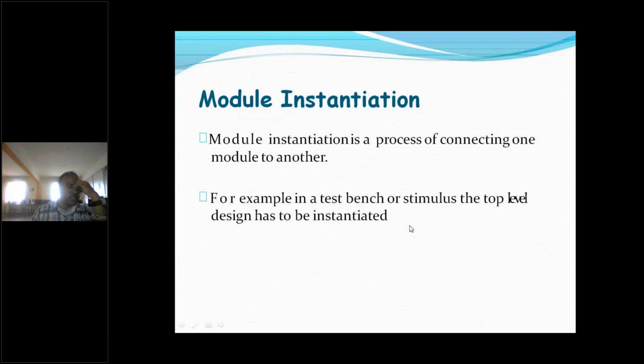What I mean by test bench is, say you are writing one Verilog code to realize one AND gate. First we take one Verilog module, then we assign inputs and output, then assign y equal to a and b. So that is the connectivity between inputs and outputs.